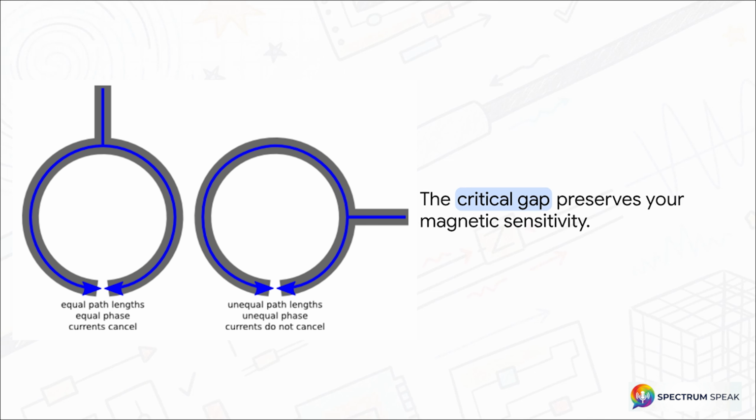But look at the physical break at the very top of the split shield. By intentionally introducing this tiny physical gap, you physically break the conductive path. Shield current simply cannot flow. It's trapped. And because no shield current flows, no opposing magnetic field is ever generated. The electric field lines still terminate right on the grounded shield, brilliantly eliminating E-field noise. But your precious magnetic field lines pass right through that gap, completely unaffected. That simple gap literally saves your magnetic sensitivity.